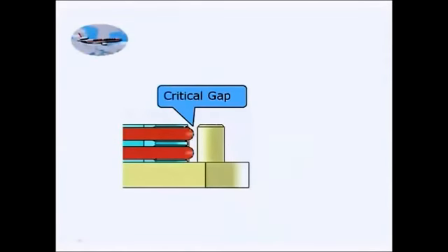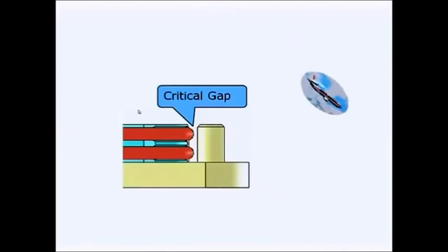So the critical gap is between the throttle pulley sector radius out here and the guide pins. We don't want this to come off. And the way that is checked is with a no-go gauge. As long as the gauge doesn't go, the gap isn't too large. If the inspector misses that or doesn't check it all along that radius, the result is that these cables could walk right off the pulley. If that happens, the engines die, and, well, you can figure out what happens next.